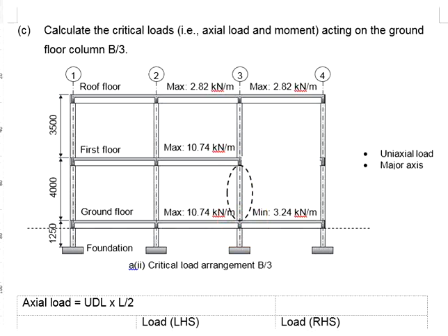You will do the same process, get the largest moment possible, which the critical load arrangements can be maximum here and minimum here, or maximum here and minimum here. Either way will do, since both spans here are the same, 6 meters. Assuming we have the maximum load here and the minimum load here, you will have fixed moments due to both beams.